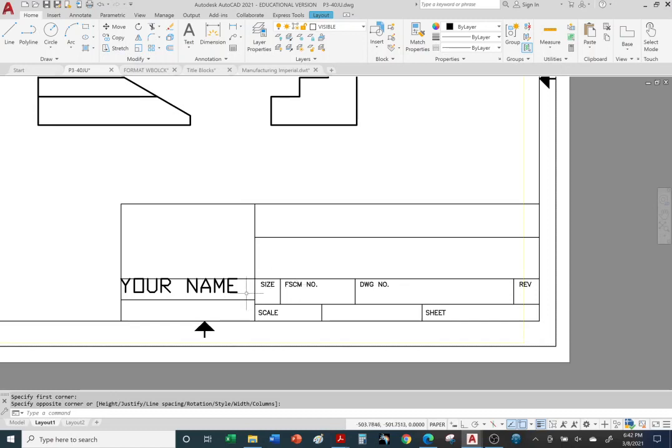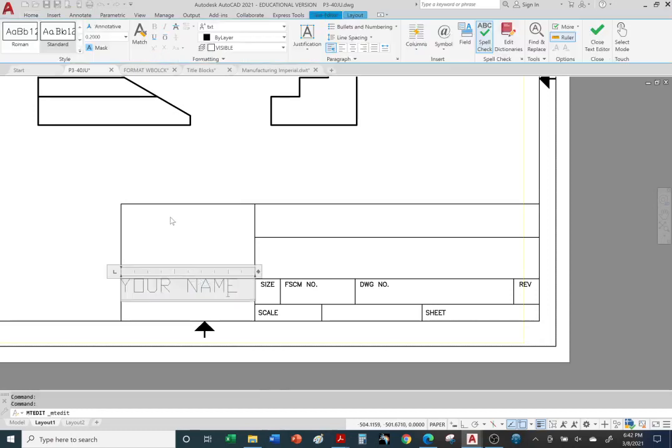If you're using American standards, inches, typically a text height is about 0.16 or 0.18. If you're following the American National Standards, they recommend you use 0.16 for your text height. AutoCAD defaults to 0.18. Just so you're aware of it. Notice here they have it at 0.200. That's actually quite large.